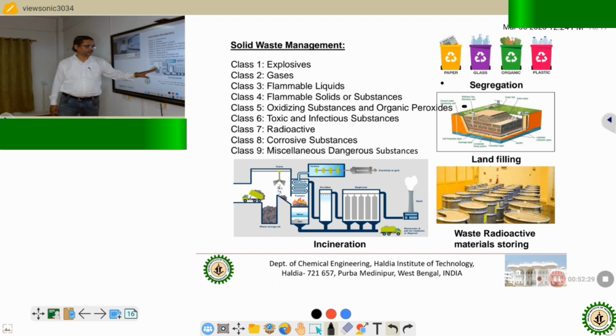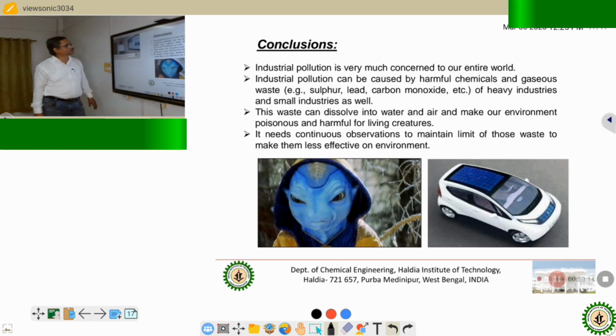In most cases, for very hazardous solid waste, we go for incineration. In that case, the solid waste is burned in the presence of, say, LPG. If the solid has a high calorific value, then that energy is captured and may be utilized for producing steam, and from the steam we can generate power using a generator. Whatever toxic vapor comes out may be scrubbed and separated out. So proper waste management is important, so that we can even get some revenue from the waste and have less hazard to the environment.